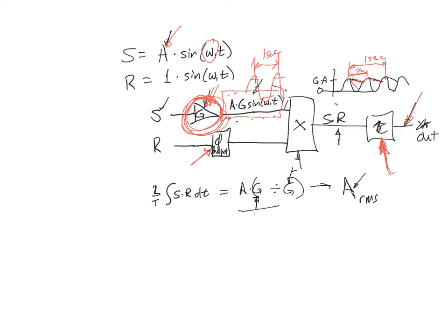So if you're just playing around in the lab and looking at dials and that kind of stuff, then you want it to be able to change something in your experiment and have this output change on a time scale that doesn't bother you too much. If you set the time constant to 30 seconds, you're going to need to wait several multiples of 30 seconds before this output will stabilize.